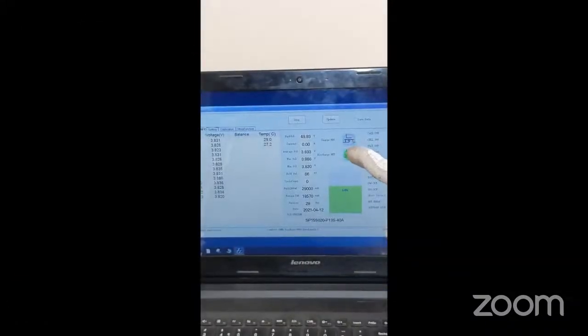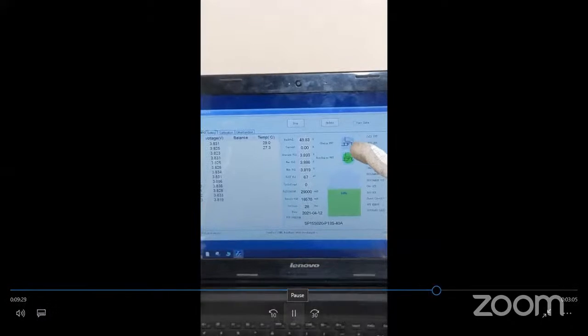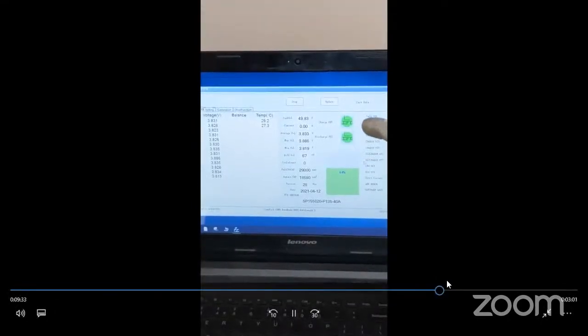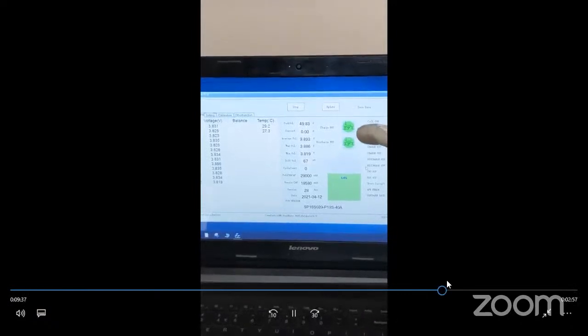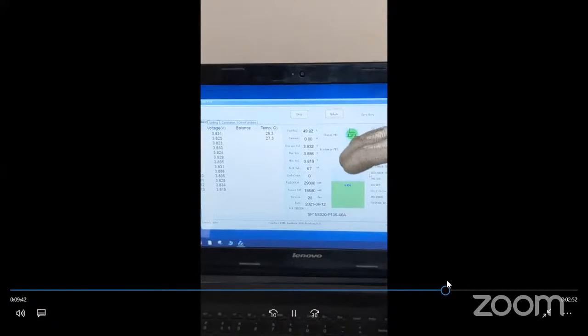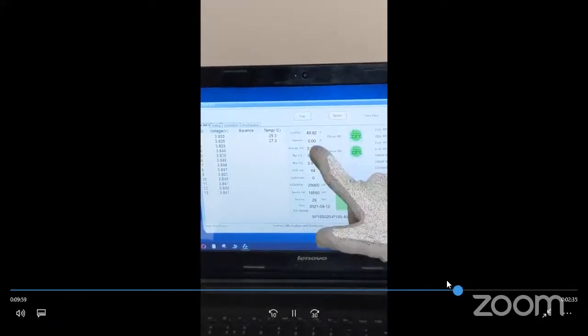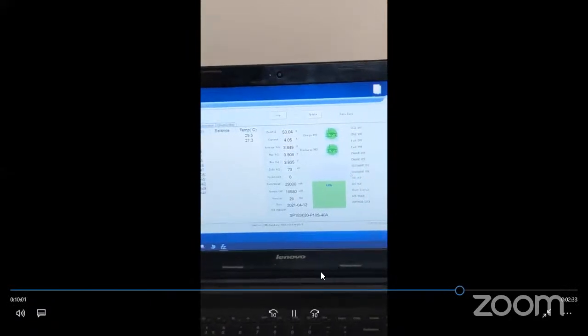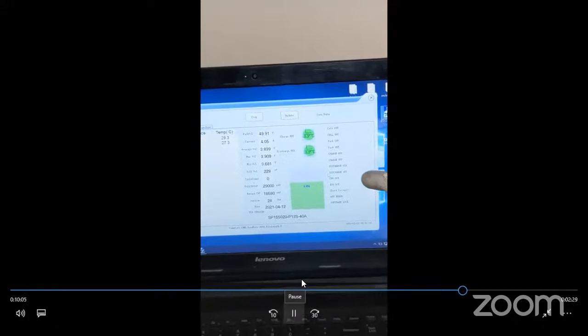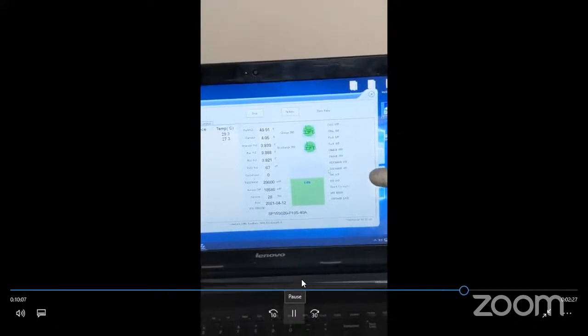You'll also get a warning on the window. Suddenly the charge MOSFET gets off, shown in gray color. The charge was in on state, and that was due to the maximum amount of current. The charger was providing 4 amps, which was above the set limit. You can see here on this window, charge over current protection.